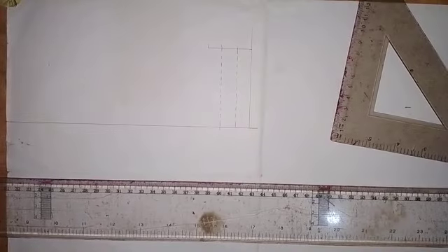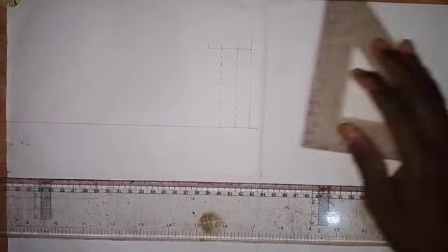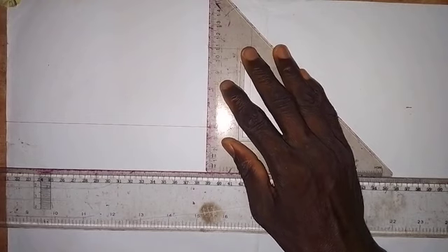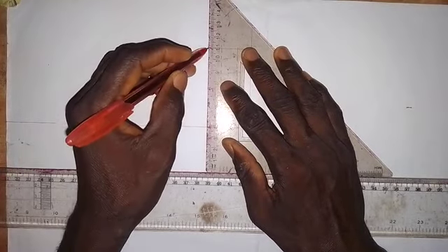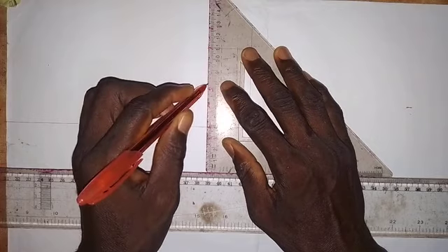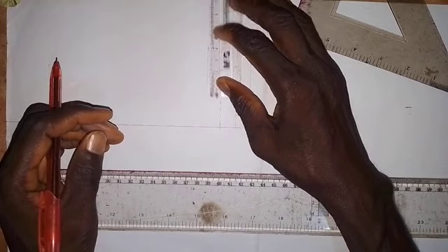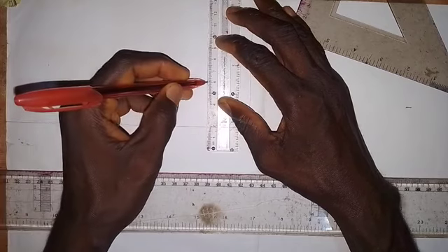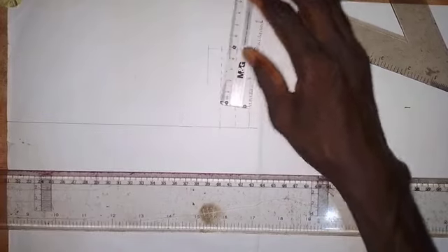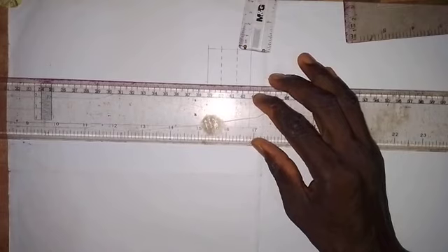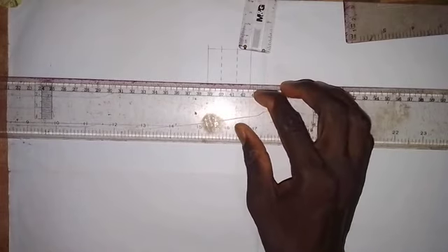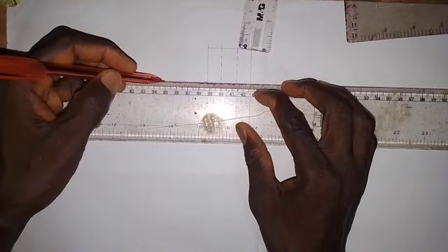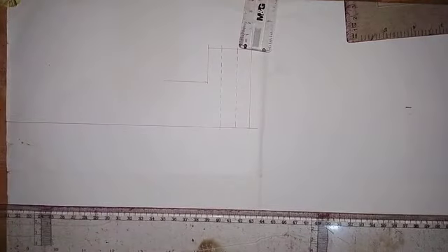So we are going to come forward here. We come to this point and we draw a short vertical line, just a short vertical line down here that can give us 30. At this point I will take a measurement of 30 millimeters. This is 30 millimeters here. So I'm going to draw a short horizontal line from this point, so it comes forward like this. Okay, so let's see the next thing that we are going to do.